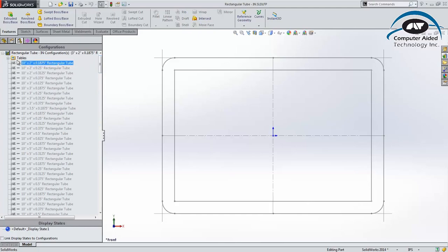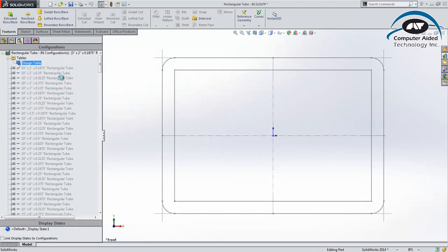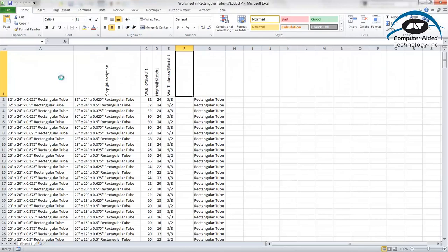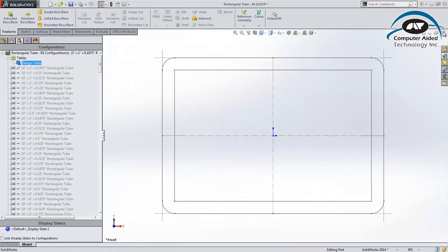To further benefit from this, all of these profiles can be created and maintained using powerful design tables to rapidly create all the different sizes. This is done leveraging simple Microsoft Excel concatenation and speeds up the entire process of creation drastically.